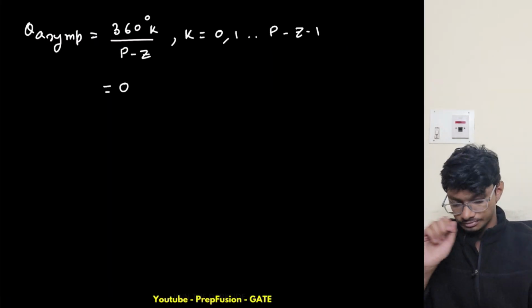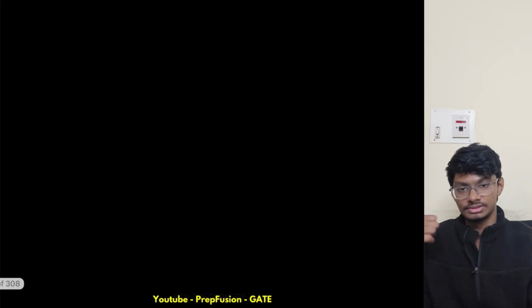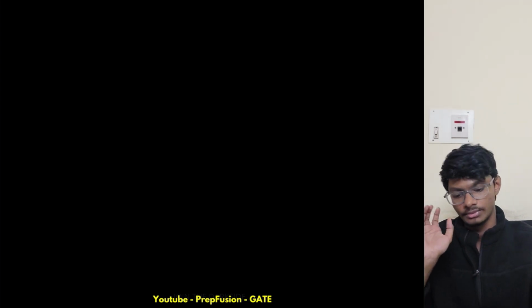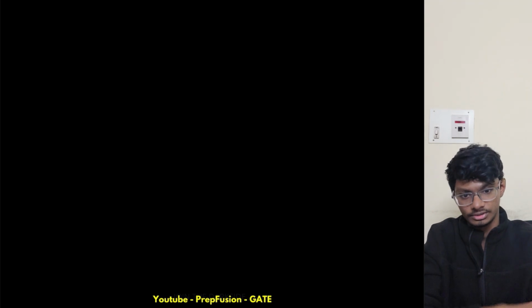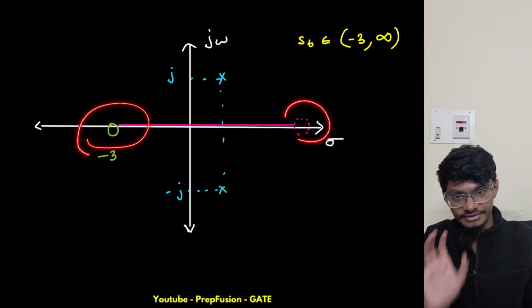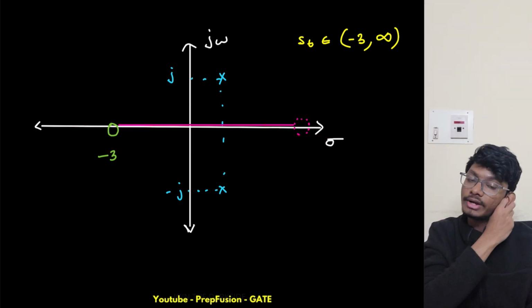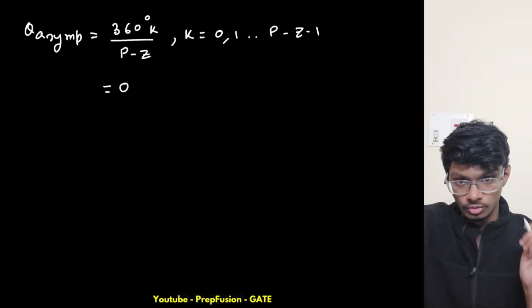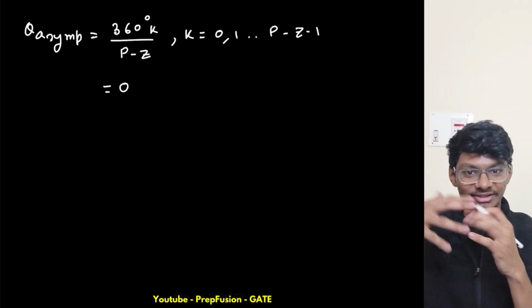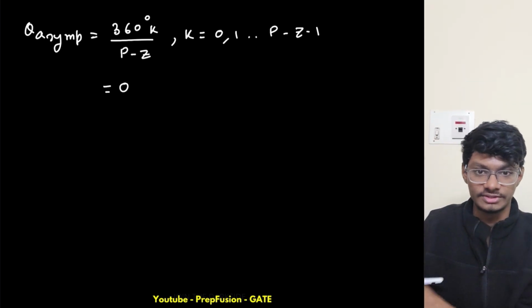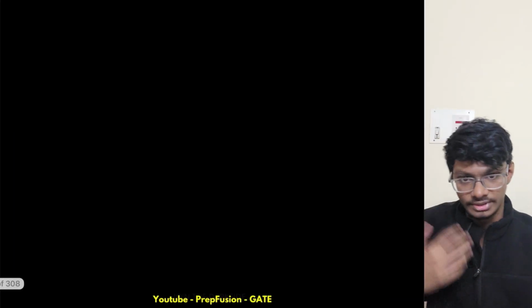This is like the previous first question, the one that was solved using the normal root locus method. So what about my breakaway points or breaking points? Here I have two zeros, this is a virtual zero but still I have two zeros, so I won't have a breakaway point but I will have a break in point. Two branches will come together, meet up, patch up, and then break in and go to their respective zeros, terminating at them.